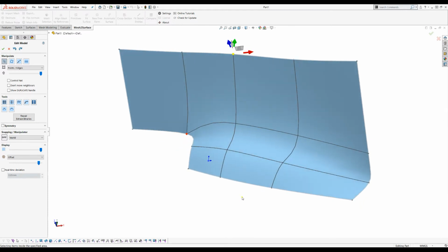So this video will just speak about our first tools here, which are called increase resolution and split edge. Increase resolution is a really simple command that takes all the visible quads that you see on the screen and splits every quad into four smaller quads. This is useful, you will see later, when you build a really rough shape of the object over the mesh, and then you want to get closer to the mesh and get better accuracy. So the command is really simple.